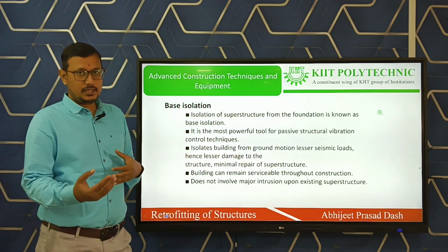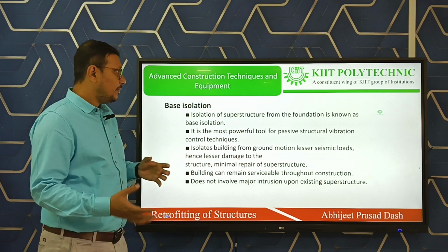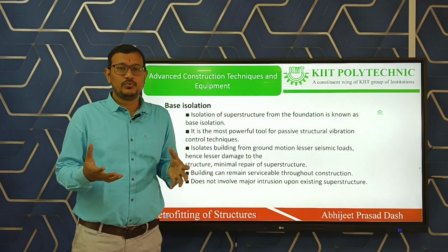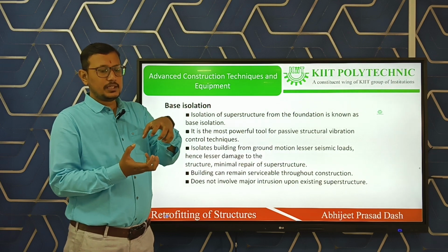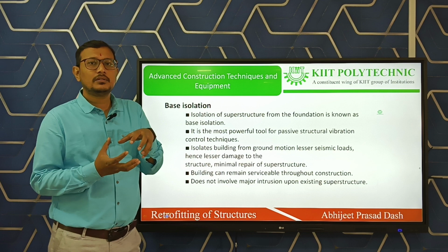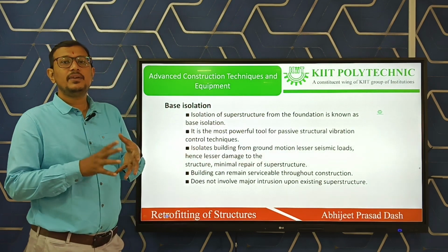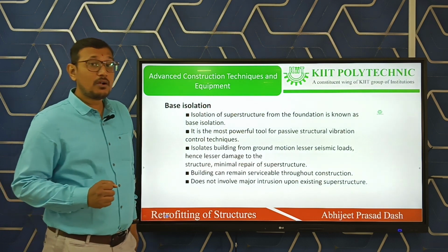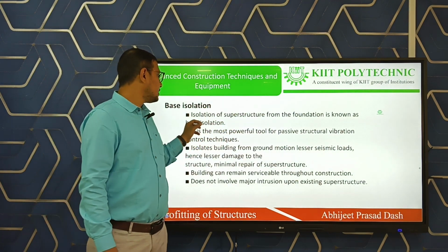Then the next technique, a global technique, is base isolation. Base means foundation. We are isolating the foundation from its footing. We are providing some mechanical arrangements to make the base isolated from the ground. You see, I will show you the figure next.